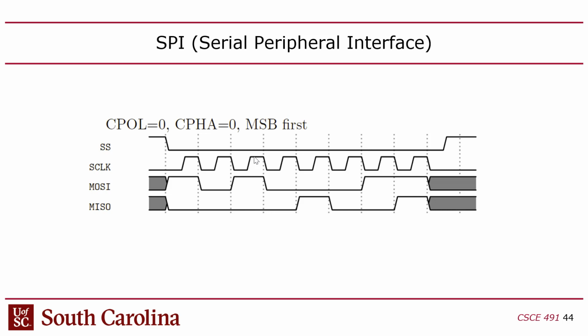But depending on how it's set up, and depending on how the channel is configured, sometimes these dotted lines will intersect the transitions, right, of the data. And that's actually, I think, makes it a little easier to read, because then you just read the state of the signal between the dotted lines, right? But other times when you look at these timing diagrams, the dotted lines will actually be offset by half a cycle, in which case the dotted lines will kind of intersect the midpoint, right? And that's where the actual hardware would be reading the state of the signal, right? Right in between the transitions, right?